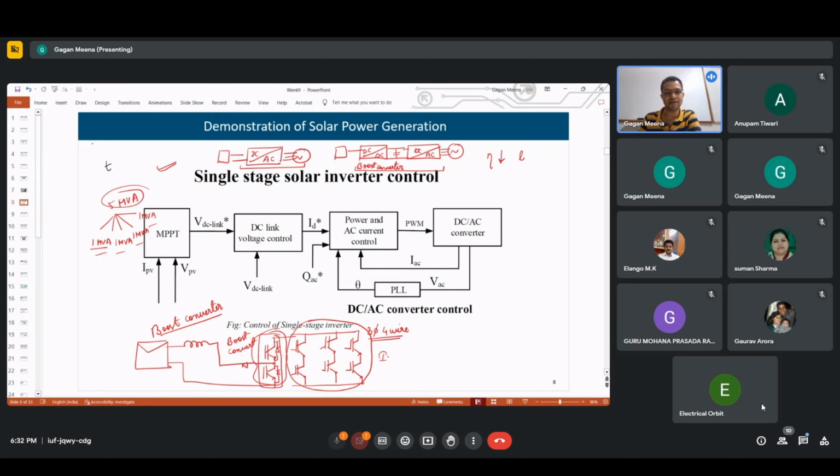We can code and program them so this DC motor will behave like a turbine. We control the chopper so it gives the same speed-torque characteristics that we want to achieve. So this is how the DFIG is emulated.